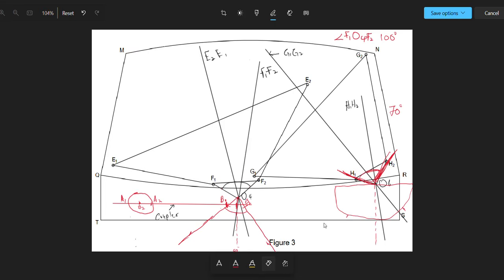And now you remove your protractor. After removing your protractor, you draw a line to pass through the 35 mark. So that's how you are going to ensure that the angle here is in a way that a horizontal coupler could attach to this link.